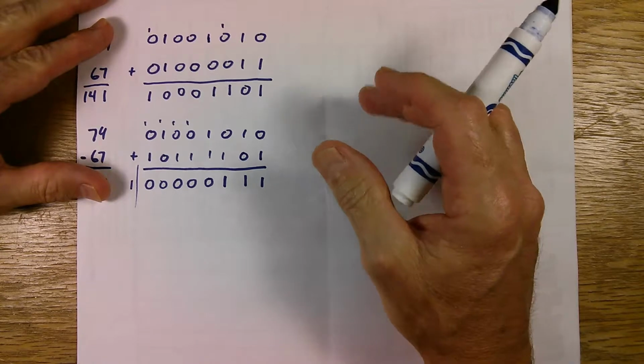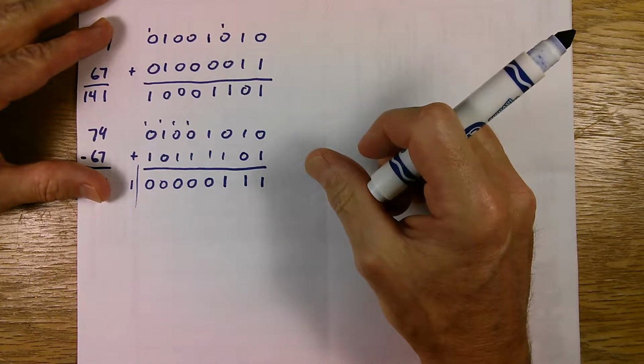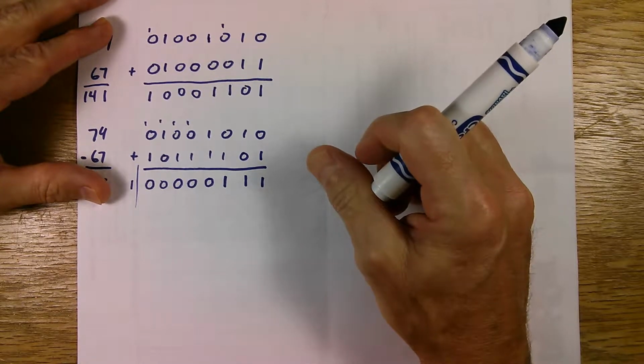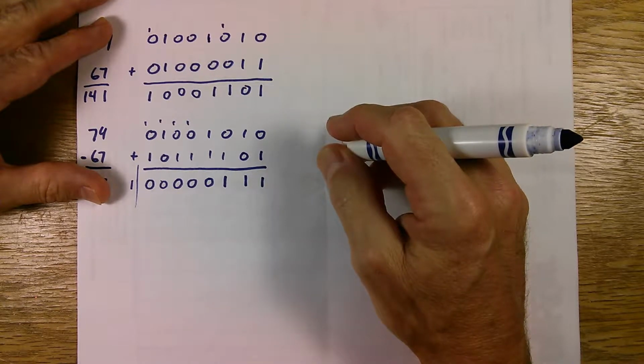So in your C code, if you declared a variable as a char or an int, the compiler treats it as a signed number. And it looks at the upper bit and treats it as a signed number. If it's a 0, it's a positive number. If the upper bit is a 1, it's a negative number. And so you've got to watch that.